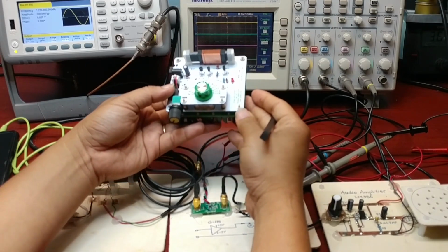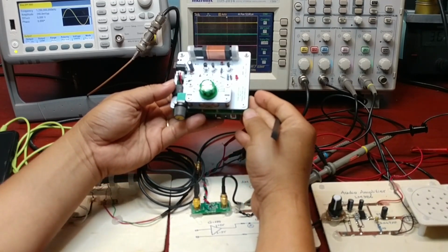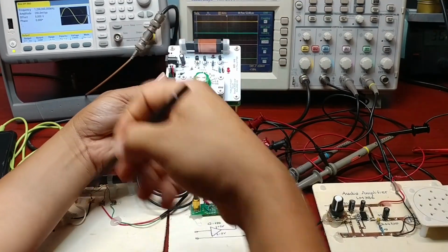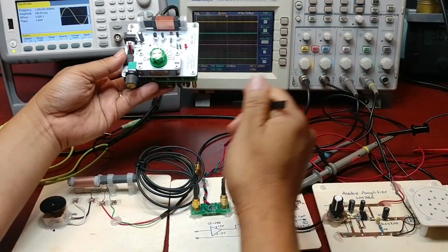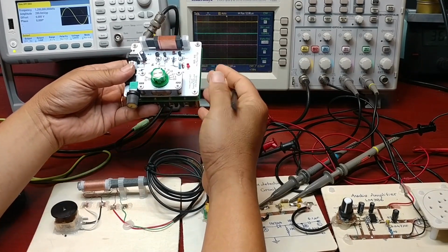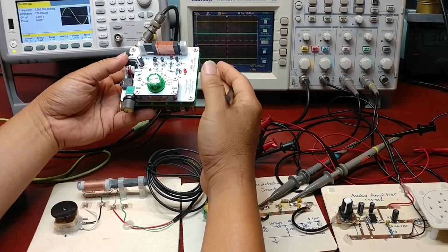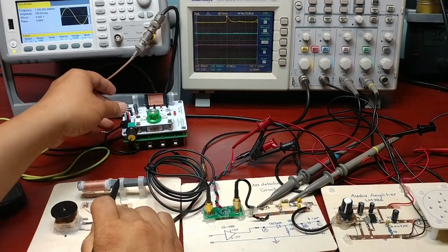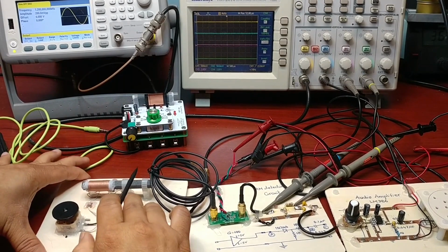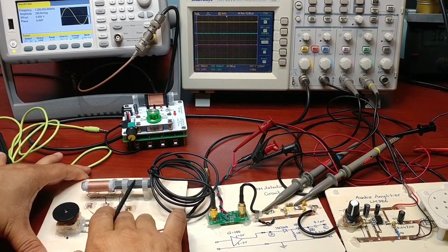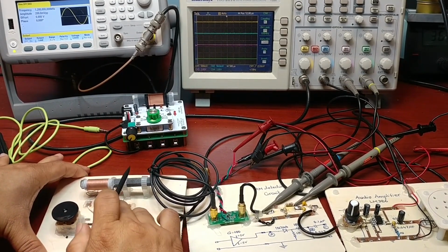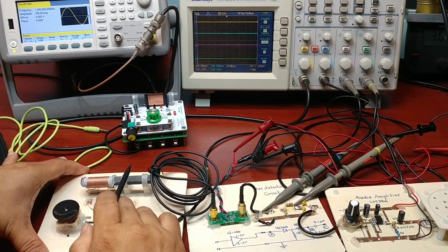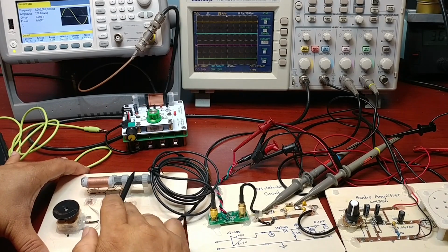Even though it uses only the magnetic field, it is able to deliver a full signal or data from a transmitter to receivers. And at the receiver, even though the radio station transmits electric and magnetic fields, they are perpendicular and propagating in space. The receive antenna can only receive the horizontal magnetic field component. The magnetic field component goes through the ferrite core, causing resonance on the LC tuned circuit, and the radio signal can be received at the output of the antenna.